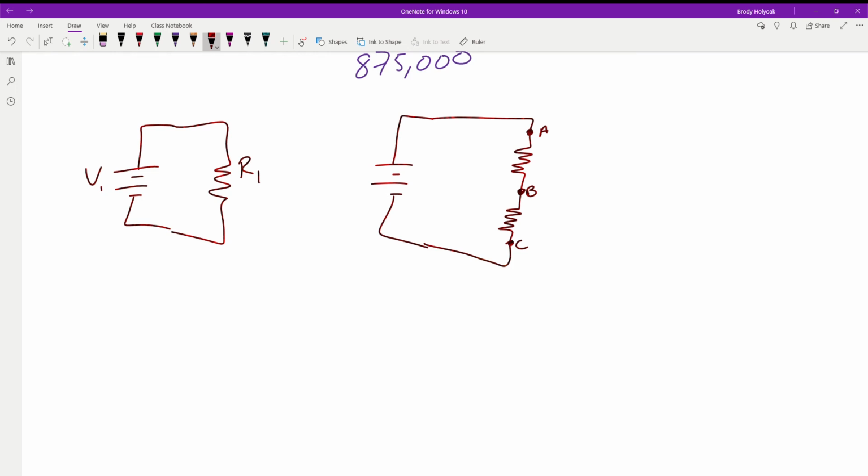Now outside of the potentiometer, we have the option to separate this point to get different measurements. But just going with the potentiometer right now, we're going to leave this connected because we can't physically break where the potentiometer is and connecting our wires. So in this case, we now have 2 resistances. And what have you been finding as you've been experimenting with the potentiometer? What happens when you measure across A and C? You get the full thing.